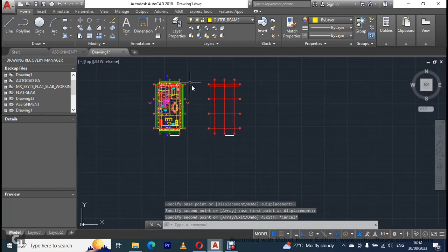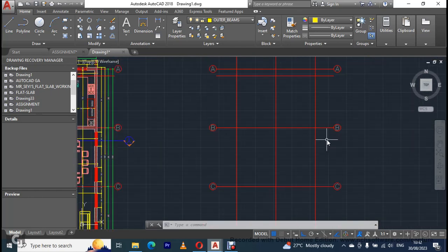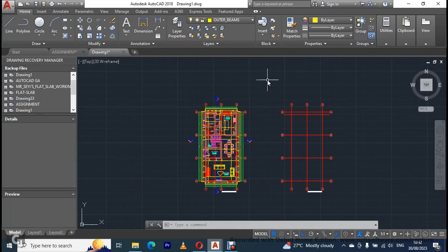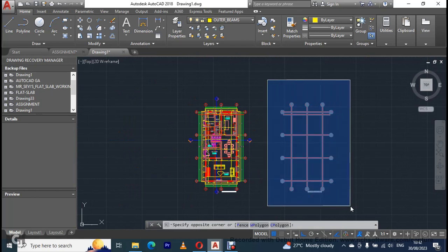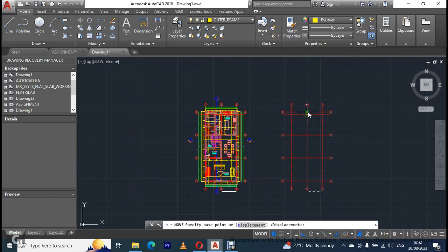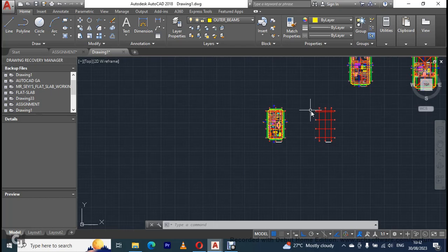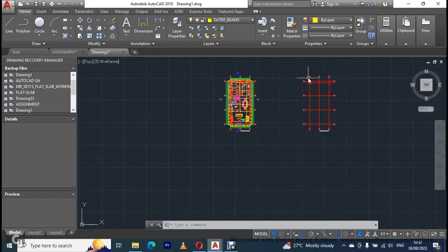Okay, so now the first thing we can do is the placement of our columns. It's very important we place our columns at critical regions. We can't just place our columns anyhow. We have to make sure that the column does not disturb the architecture of the building, and that it does not disrupt the beauty. You get how the building is supposed to look normally. We have to make sure that it doesn't disrupt it. Alright, so to do that,